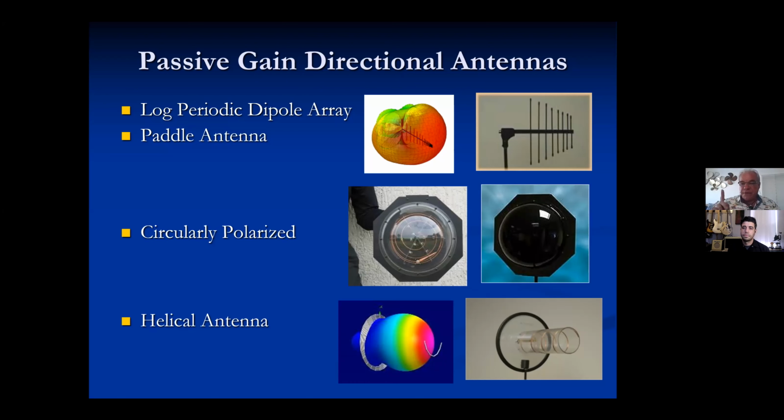But if it's an FM system, which all the in-ears on the market that are used as in-ears are, the only one that's not, to my knowledge, is Electrosonic's digital duet system. But for FM, there's a function called the receiver capture effect. The FM in-ear receiver will only lock onto one of those antennas at a time. And just like a cell tower, when you go from one to the next and you roam to a different node, the receiver will not switch and feed audio to the in-ear buds until the signal from that secondary antenna is 6 dB hotter than the one that's locked onto. It's just a function of FM.